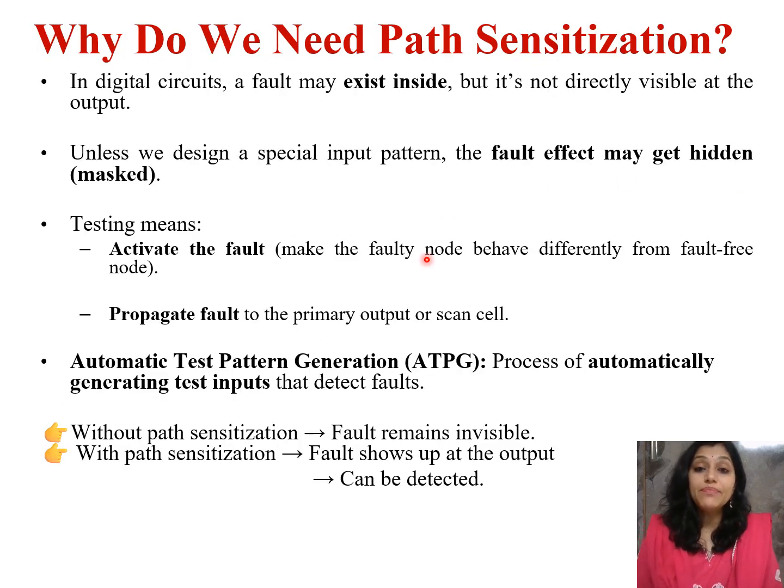Then why do we need path sensitization? It is one method of testing of the chip, used for generation of test patterns. In digital circuits, a fault may exist inside, but it's not directly visible at the output. Unless we design a special input pattern, the fault effect may get hidden or masked.